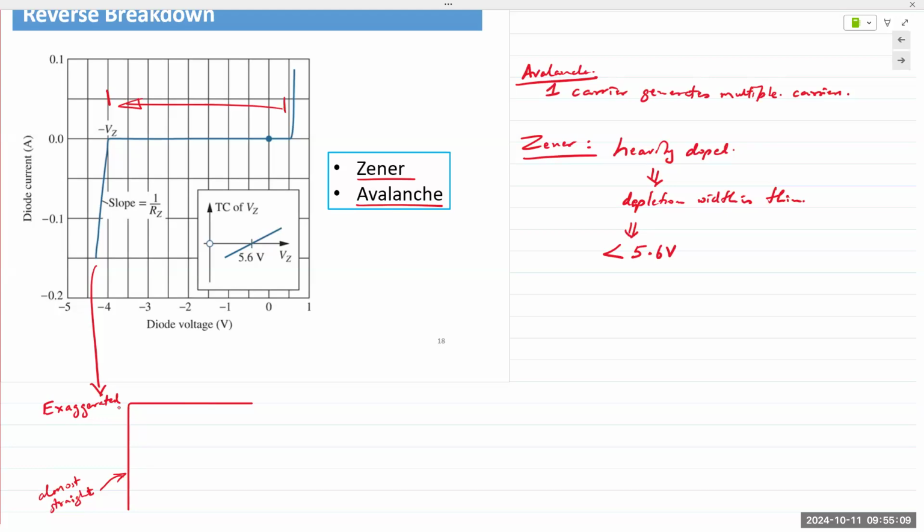It depends on the doping concentration. If you have a silicon wafer, first of all, there are a few applications where we still see discrete components, but it's getting harder and harder to find discrete component manufacturers because it's more expensive. If you have a silicon wafer and you're trying to make a component in there, we can't simply make one diode with a different concentration. Everything has to be exactly the same because you're simply processing everything together, right?